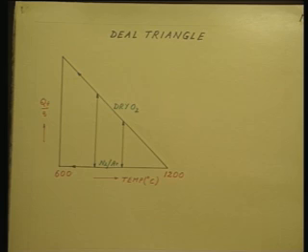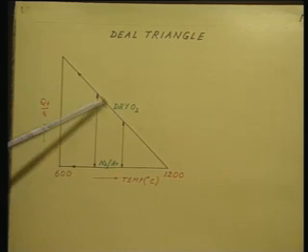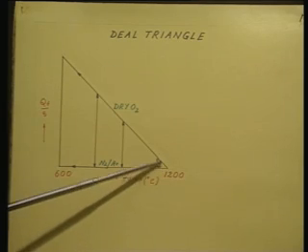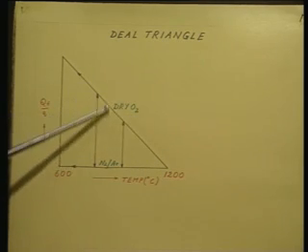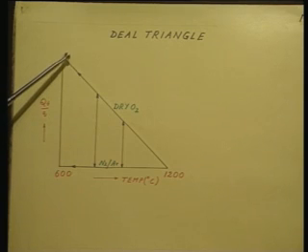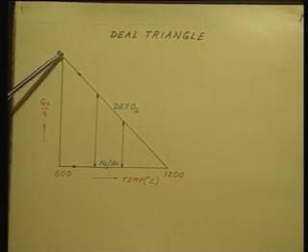Now, let us say that the oxidation is taking place at a very high temperature, 1200 degrees centigrade, and now from this temperature the sample temperature is being lowered, and while reducing the temperature still an oxidizing ambient is being maintained. Therefore, there is the possibility of having incomplete oxidation. So, this is the path it traces. As you reduce the temperature, if it is done in dry oxygen ambient, this is the amount of fixed oxide charge you get, which is very high, greater than say 10^12 per centimeter square.